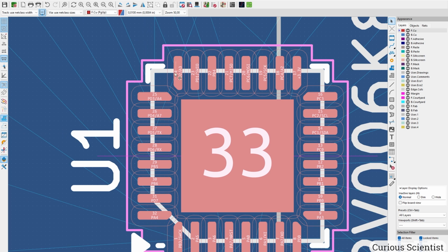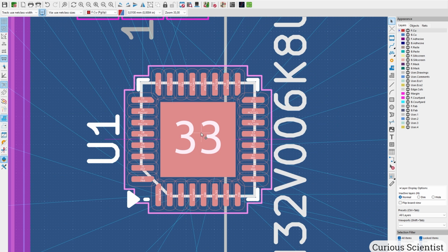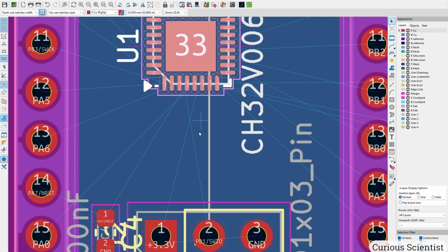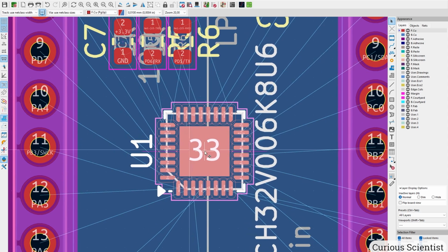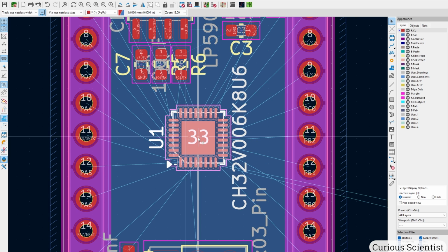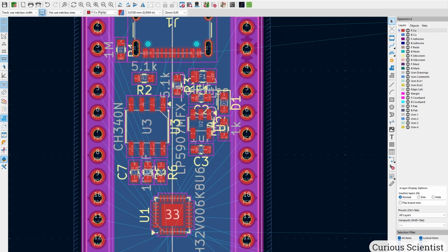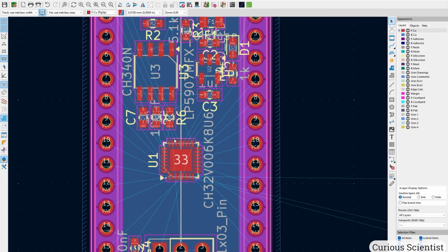Pin 24 is facing upwards and pin 1 is facing down towards the bottom of the board. So I grab this and I put it on the center of the PCB, somewhere here. Again, this is just a preliminary positioning because later on I will wiggle all the parts here and they might end up at a slightly different position. But the chip, I want it to sit at the center line of the board.